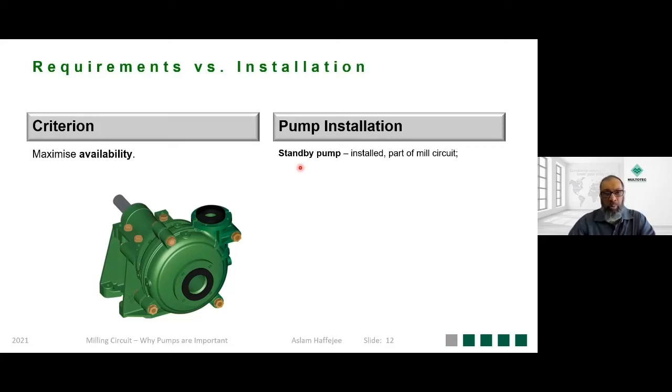So should your operational pump be needing overhauling, that pump is stopped, isolated with a valve, and you switch over to your standby pump. So there's hardly any downtime if you implement this method.